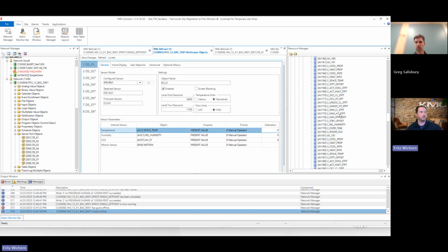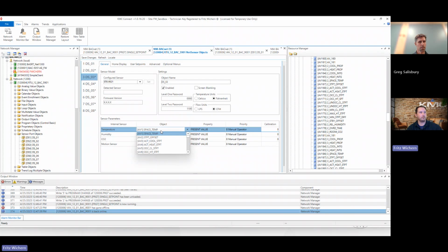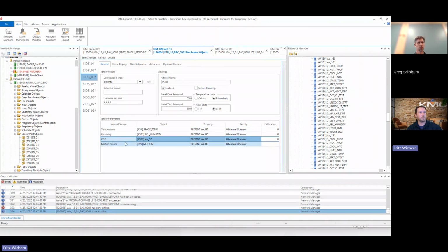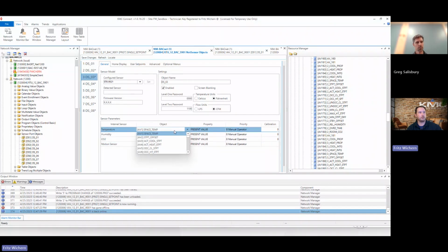So the big thing when you're using multiple net sensors with that distribution board is that you've got to come in and create these points and then come into each of your net sensor configurations and actually reference each of these temperature, humidity, CO2, the motion sensor to those extra points that are found here. So if this is 3, I'd scroll down and look for 3. It looks like I'm in the 7, so I'm just going to click one of those.